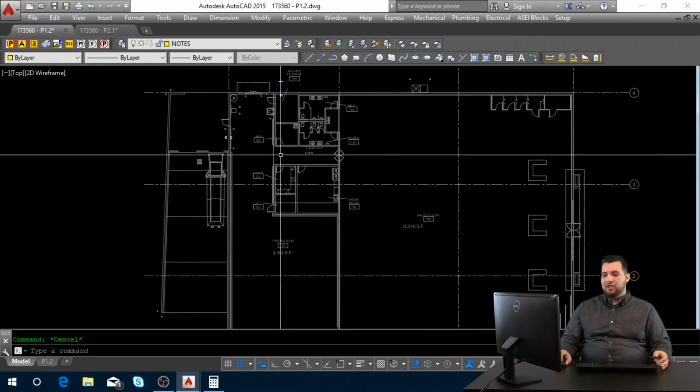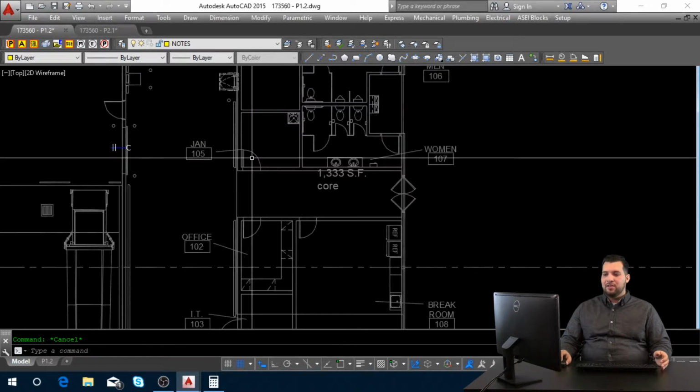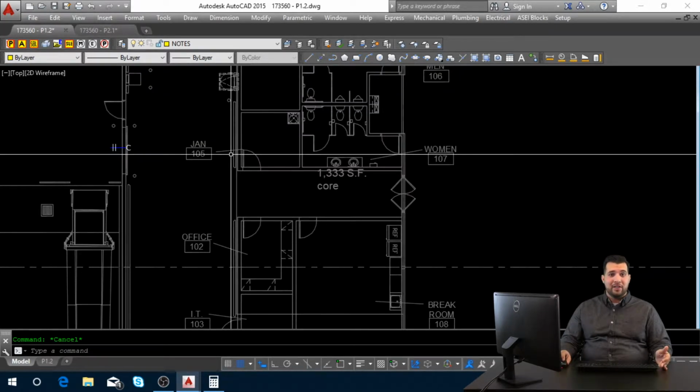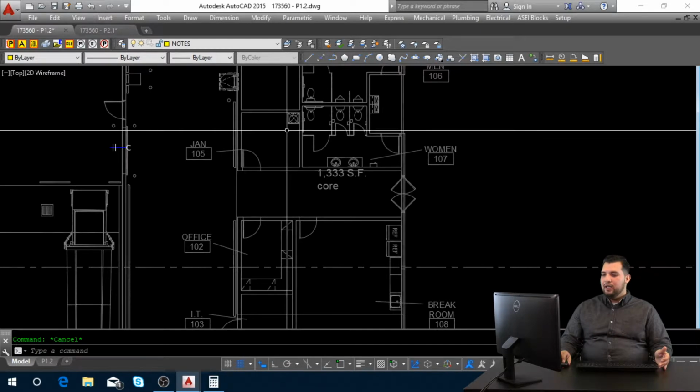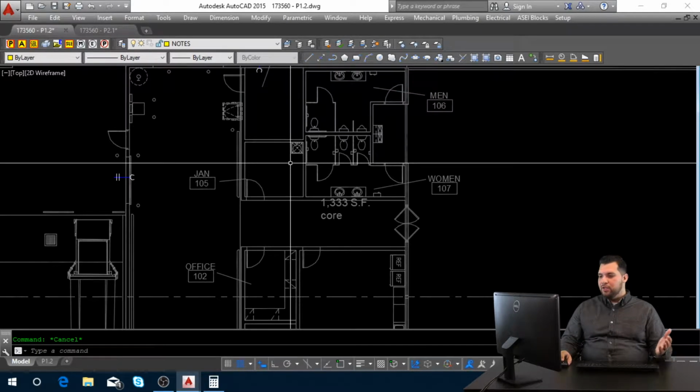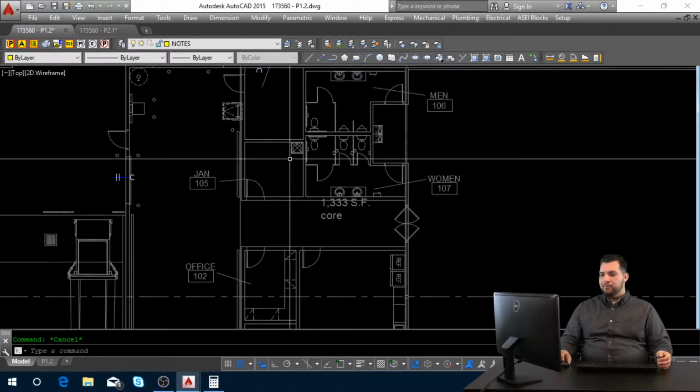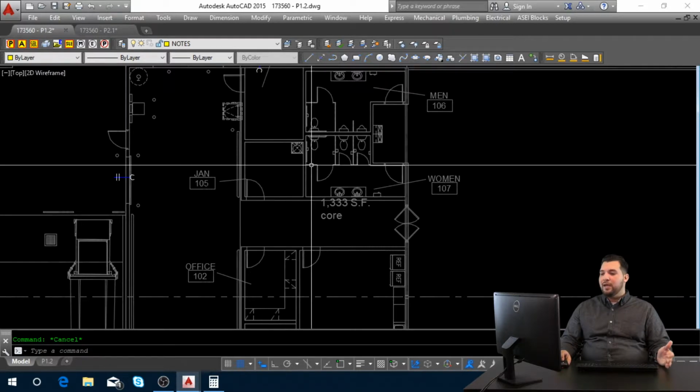So you want to go through the job. I know specifically these are the two pieces of equipment that we're going to need for this specific job. But you want to usually go through your whole design. If you do see any boxes or squares that you don't know what they are, they're not tagged, you want to ask the architect. Make sure that you know exactly what you need to schedule before you actually schedule it.